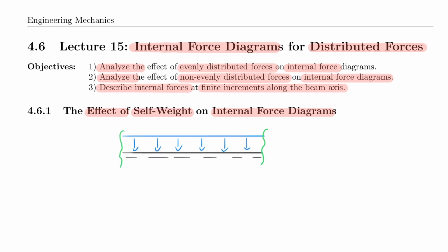And of course, in reality, I release internal forces if I do that. And the internal forces that we would release would look something like this. You remember this from your study card. I have the shear forces on both sides because I cut on both sides. And I also would have normal forces on both sides, which I am not trying to calculate right now, but I want to think about how they conceptually would look like.